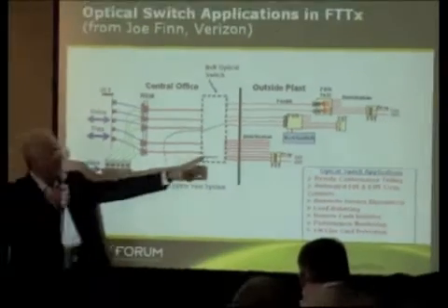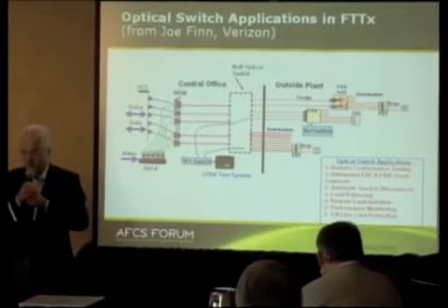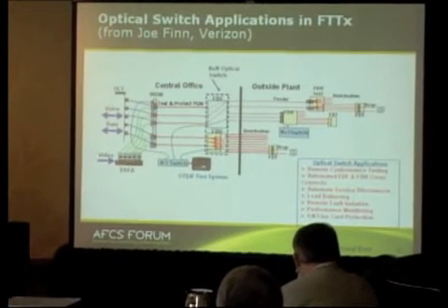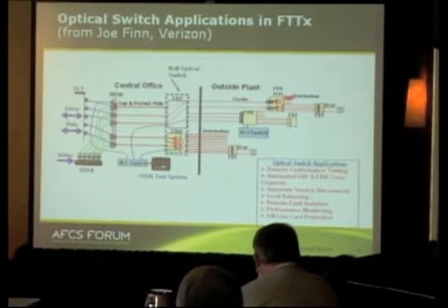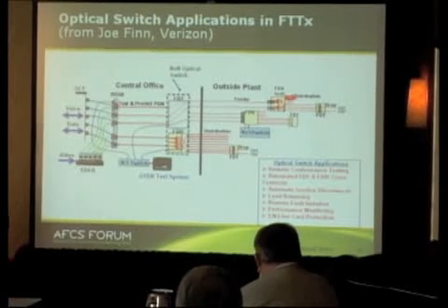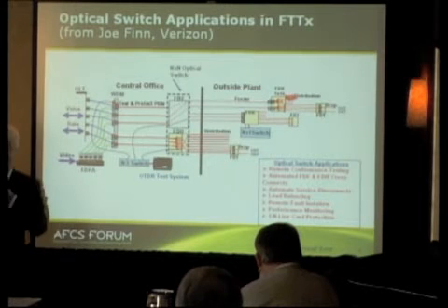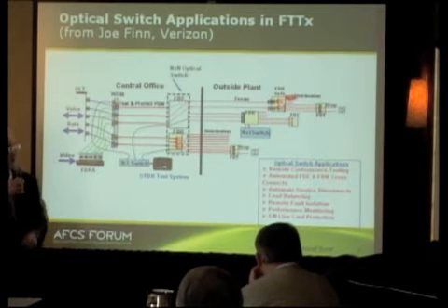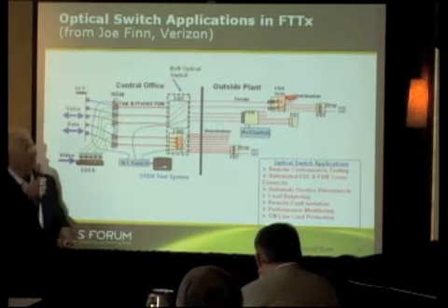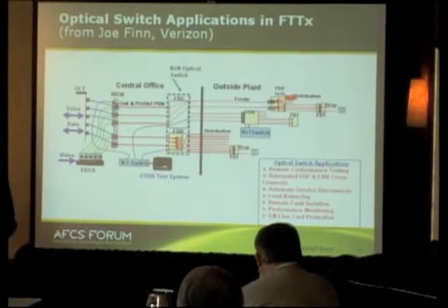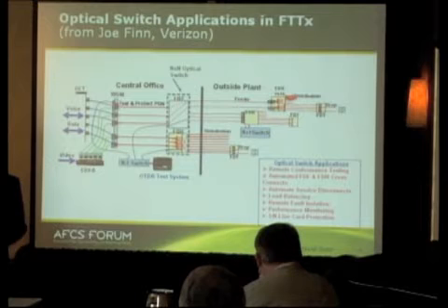And this is more like a central office application where, let me step through a few times, we're using the N by N switch either for protection of the PON or in some instances potentially for load balancing. Now, one of you, I guess the gentleman from the Light Brigade, mentioned the possibility of optical switches actually inside the FTTH. That's also being studied and proposed by several people.